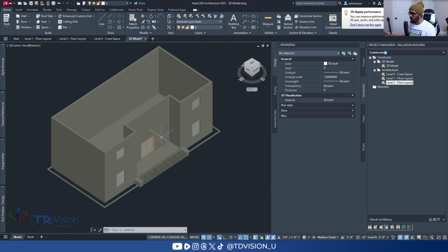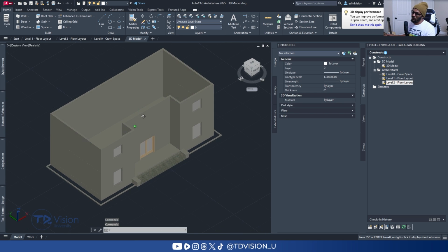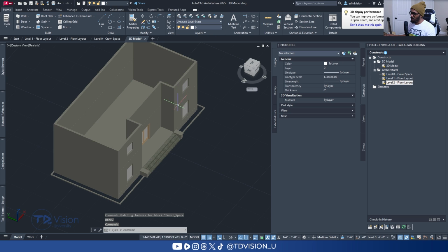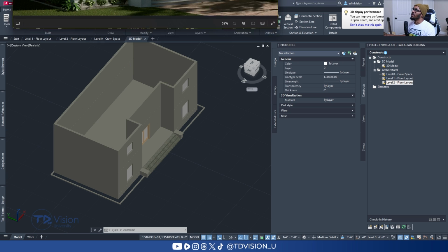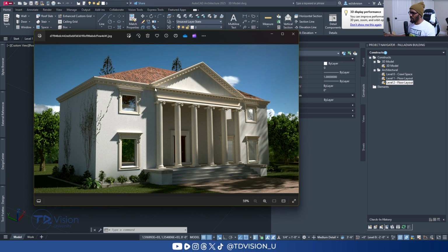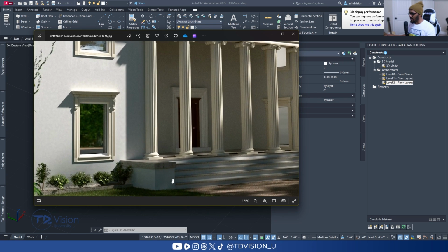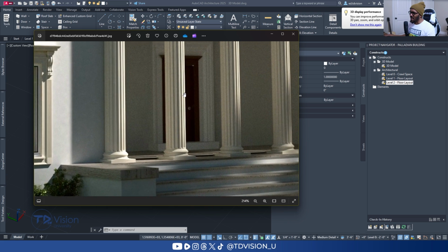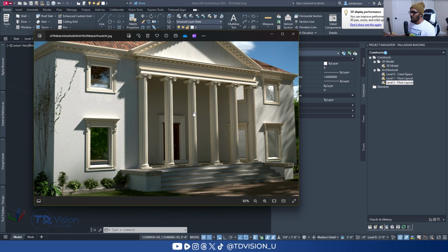All right, now first thing is, if you notice, there's no floor on the second floor, so we do need to add something in there. But I also want to add a little piece of wall, or kind of an arch piece of wall up here that would represent this portion here and also be extending up into the roof at some point. But then I'm also noticing that for the columns, I'll need to have the slab on the porch here extend out some more too, to be able to hold these massive columns in that location. So let's see if we can get all three of those things done before we get to the roof.